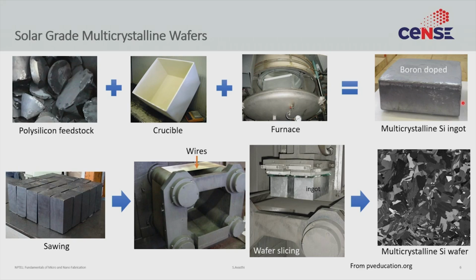So you get this ingot. You sort this ingot into individual ingots of a certain size. The most popular size for silicon solar cells is the 6-inch wafer, around 156 mm. So this huge ingot is cut into these cuboids where the cross section is 156 mm. Now each of these needs to be sliced into wafers. The way we do that is through wire sawing.